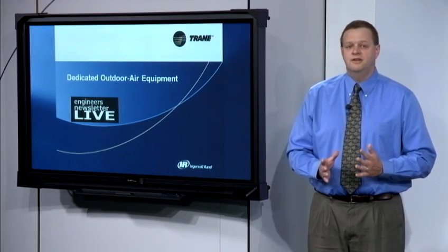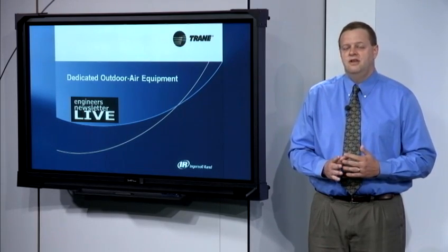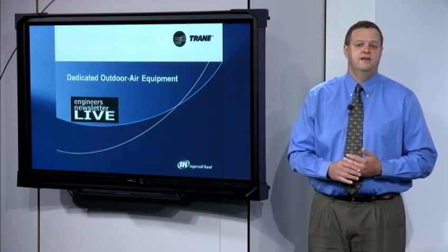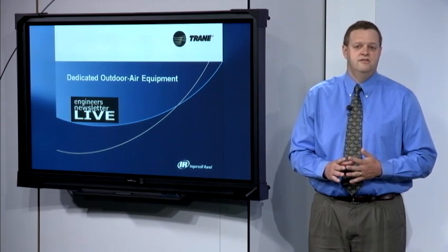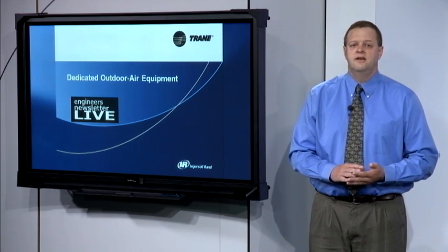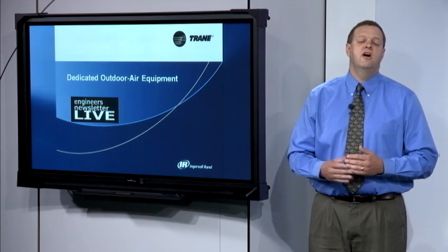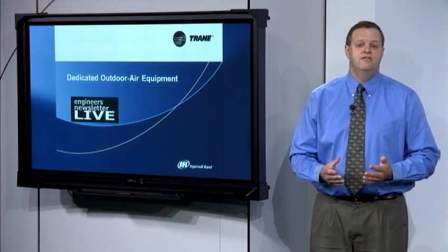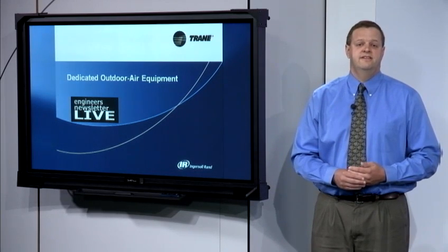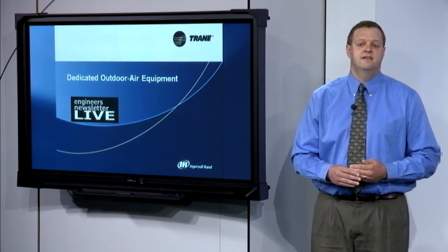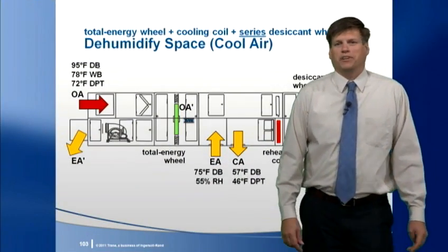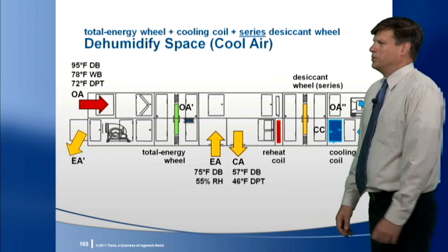Air that leaks out of the building due to positive pressurization and air leaving through local exhaust fans decreases the exhaust airflow coming back to the unit. And if demand control ventilation is used to reduce intake airflow, the central exhaust airflow must also be reduced to avoid negative building pressure. For some applications, there may be little or no centralized exhaust airflow to regenerate the desiccant, which renders it ineffective.